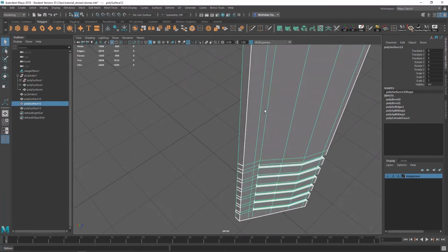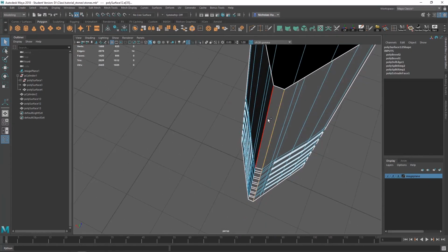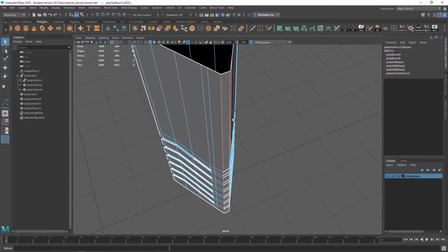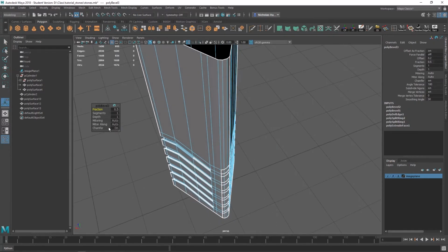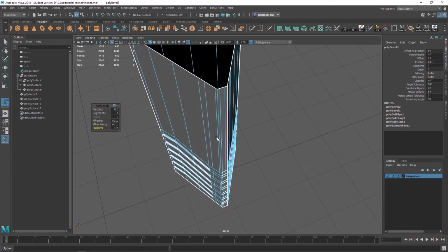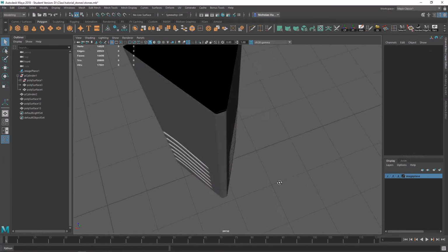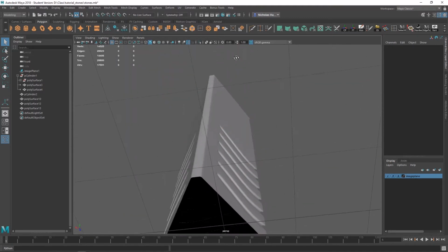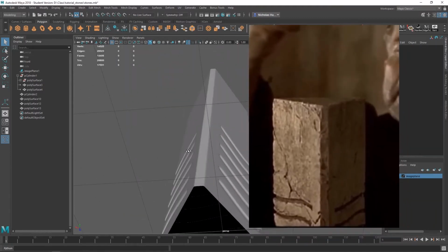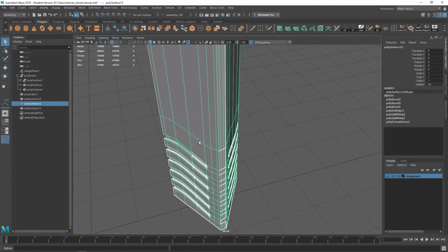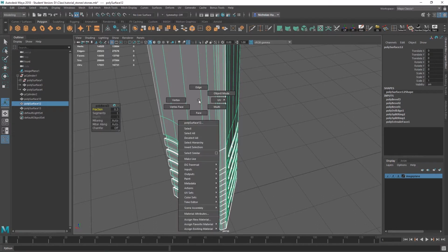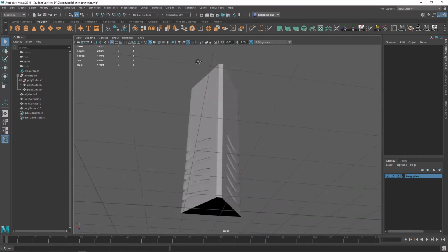Go over here, click these edges, and bevel again. So we just did bevel, so we can tap G on the keyboard to redo our last command. So G, we'll do a new bevel here. I'm going to turn chamfer off, and this should be sharp enough. Let me look here. It's probably all right. I could probably go a little bit sharper. So I'm going to select this, tap T, and fraction maybe 0.3. That's a little bit more refined.